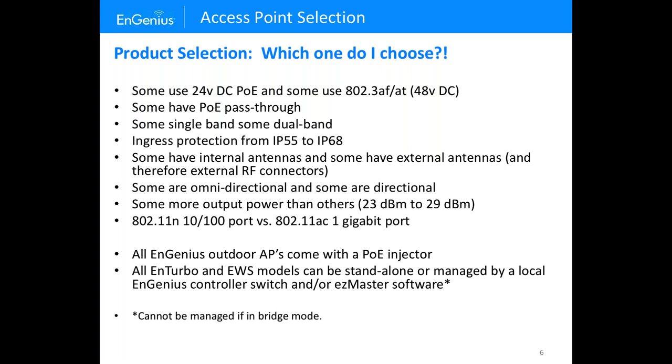As an access point, this is pretty much not an issue. In other words, as an AP, you never really want to be above 23 anyway. But for bridging, it could be useful. For example, we have some that have relatively low gain antennas, but can go really high power. That could be useful in some cases.